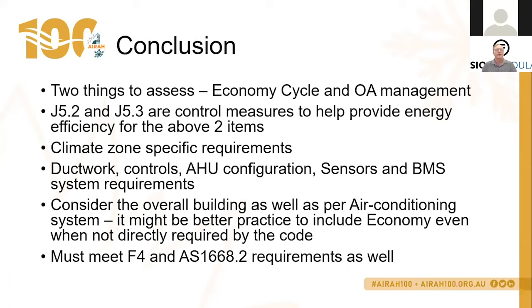It's not uncommon for large FCUs in ceiling spaces that would require an economy cycle to be split into two smaller units that serve the same space in order to fall under the economy cycle limit. No adequate spill air path can be provided and or increasing the outside air ductwork is not feasible. No, it doesn't assist in energy efficiency and reduction of energy usage in the space. Yes, economy cycle is strictly done based on individual system sizing.